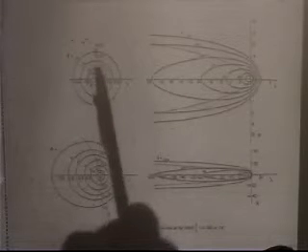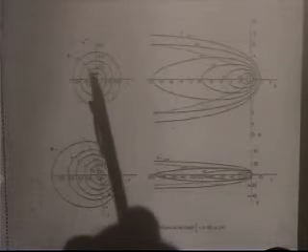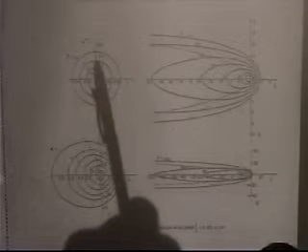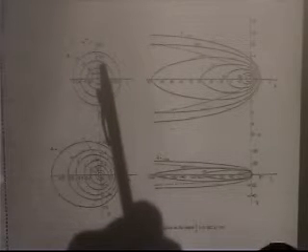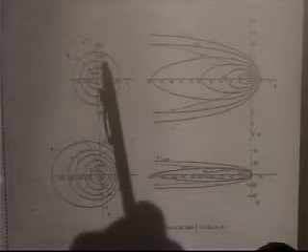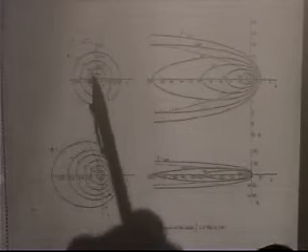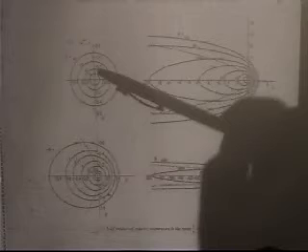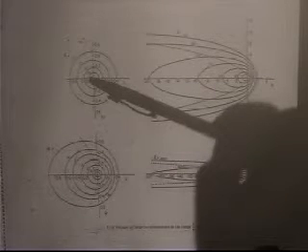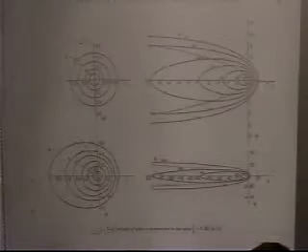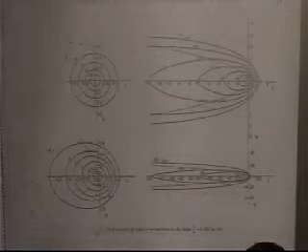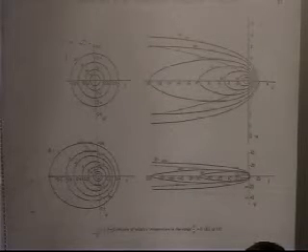Here, if you look at the heat affected zone, the maximum growth, let's say this first circle is the fusion zone, and going two isotherms out is the heat affected zone. I'm going to define coming up to that temperature as the heat affected zone. You can see that the heat affected zone grows to its maximum extent when the weld pool is still present. And that basically says the heat affected zone is growing on the heating cycle when the weld pool is still present as a heat source heating up the surface.